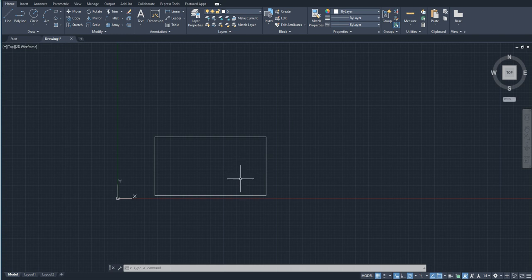Line tool is basically one tool that you'll be using a lot repeatedly in your file because it's the most used tool in AutoCAD. So let's just begin using the line tool. There are two ways basically to enter any command in AutoCAD. One, you can just type in the command using keyboard. Second, you can go towards that icon of the command and select it from there, just like using Paint. So if I want to activate the line tool, I go to the home panel here in the draw section and select on line.